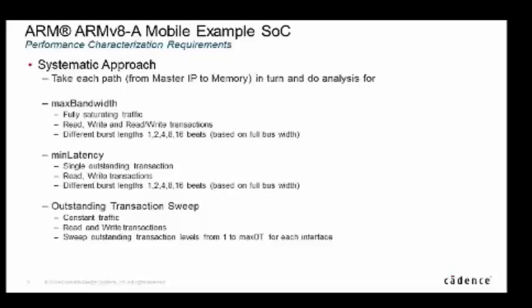The same for minimum latency, and this gets interesting. Again, we looked at this and went, hold on a second. For writes, we've got consistent latency, and for reads, we've got these blips. When you actually research into it and figure out what's going on in the simulations, it was very quick for us to realize it's a DDR refresh. So as the DDR refresh pings in, suddenly the transactions take a quite dramatic hit on latency. And I think a lot of the tool learning is about learning your IP. Your IP is complex, it's almost getting to be like analog, right?